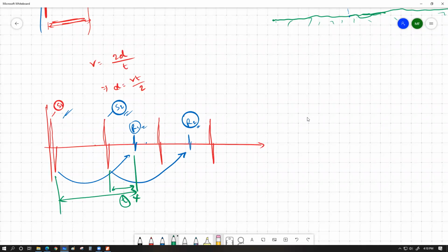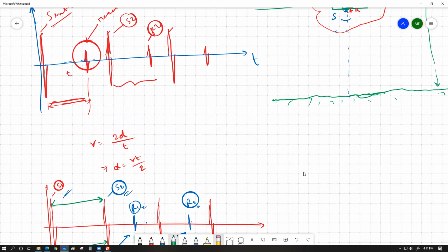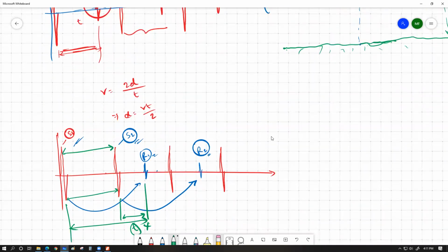So what is really important is that as the ship travels from shallow water into deeper water, we must space this out more. Physically spacing out on the graph means that we must send out the send pulses with a bigger time gap, which means each send pulse should be sent after a longer time delay. For example, if we are sending these pulses at 100 hertz,